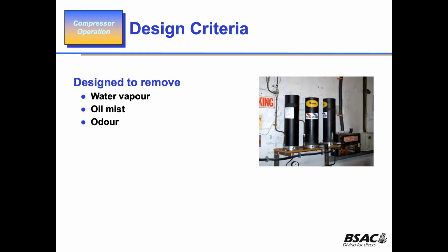Internal corrosion is the main reason. But remember, you're going to pump that cylinder up to 200 bar, then drop that pressure down to maybe 50 bar. So again, thinking of the gas laws and the dew point, if that air isn't dry, any moisture in the air is going to come out of suspension and condense out in your cylinder.